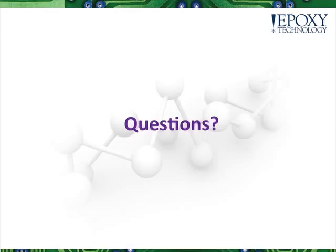I usually like to tell people, have a witness sample next to their part, and with that witness sample, press it afterwards, 24 hours after, and see if you have any liquid coming out the sides. If you have a really liquid or a lot of movement within that sample, you may have skin over, and you may want to double check your intensity at the bond line.